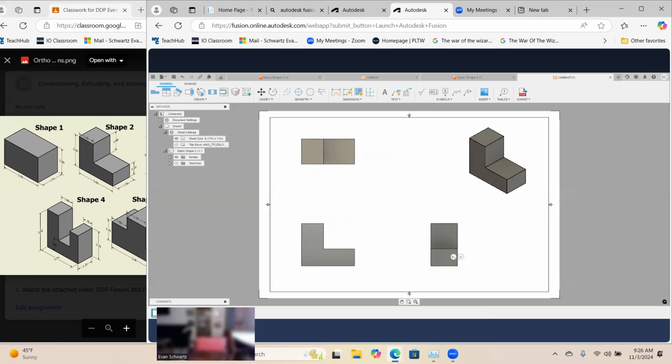Okay. So what we're seeing here in the top view are these two top faces combined. Okay, we're going to be making drawings of these. This is called a multi-view drawing, as well as an assembly drawing, but I'm just explaining what you're seeing. So you could see all of the front face like this. You can see the two top faces. Here you see the two right side faces, this and this here. Okay, combined. So now we're going to pull our dimensions.